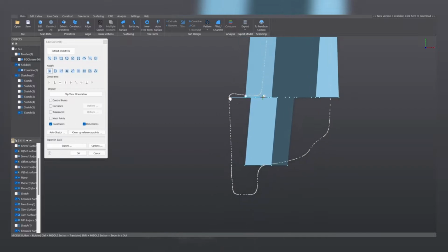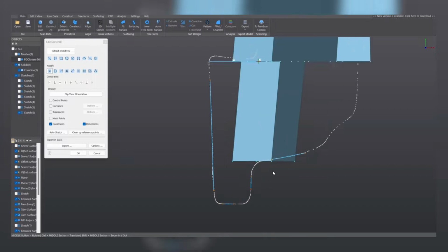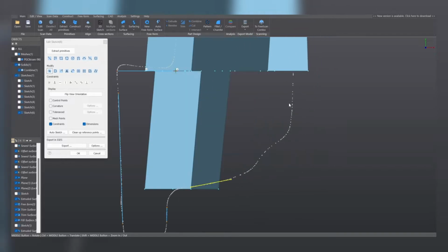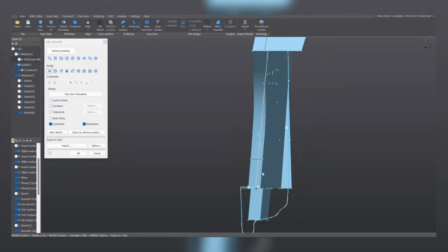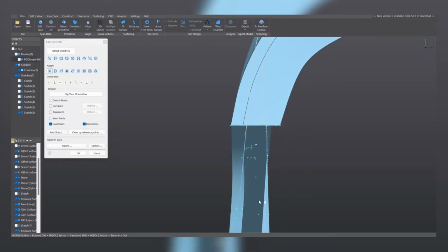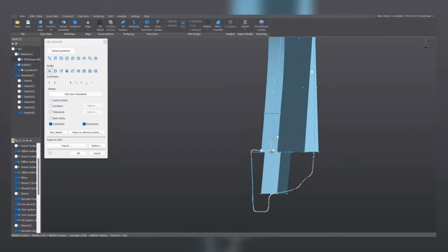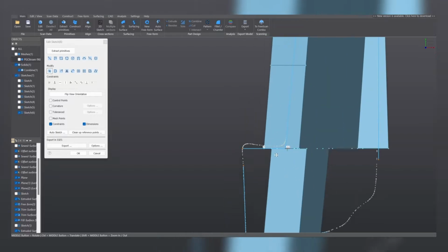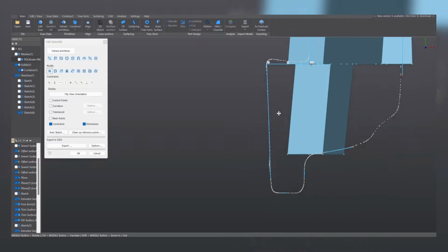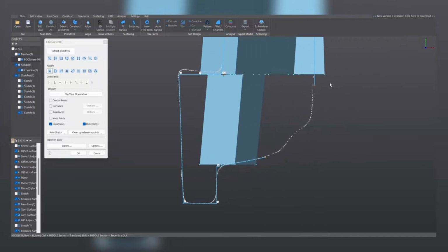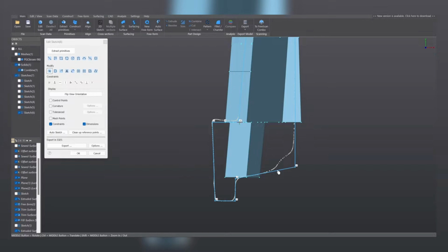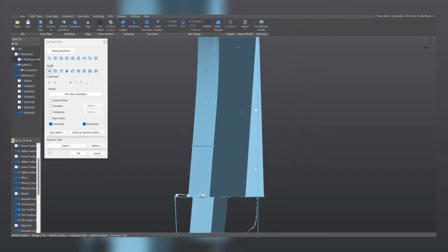I'm going to make a horizontal line here, and let's best fit lines here and there. Actually, yeah, this is a line, perfect. And let's do the same with all this long line here. This looks quite good. Let's select more points. That's it. Okay, and now let's close the sketch. With the Control key, remember, you can connect two endpoints easily. Here, let's assume that we can ignore this deformed shape of the mesh.